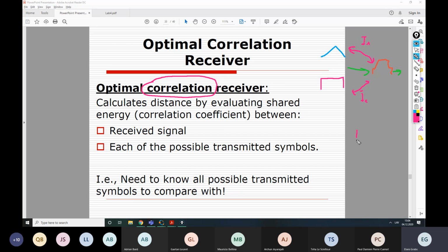Then we compare them to each other and select the one that is higher, because it's more probable that indeed this signal was originally sent, since this signal is more similar to this. Once again, it is possible that actually the opposite happened, but the probability of that event is lower, right? So we choose the maximum probability events. In this case, I'm assuming that it was actually triangular, but because of the noise, this form has been distorted to this. And we need to calculate this similarity in a certain way.